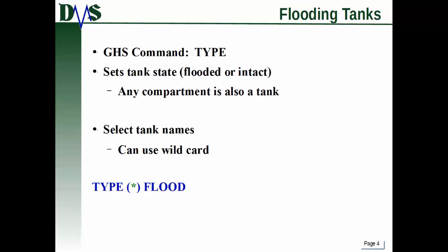So the water line within the tank will exactly match the water line outside of the vessel, accounting for vessel trim and heel. Now, once that's done, GHS then re-equalizes the vessel. So it's basically a lost buoyancy method in which GHS is constantly re-evaluating tank contents and tank levels.